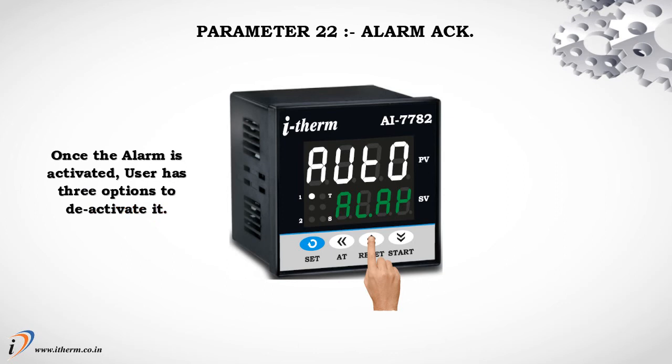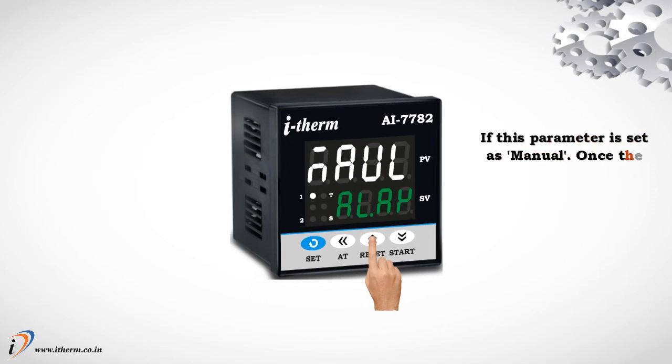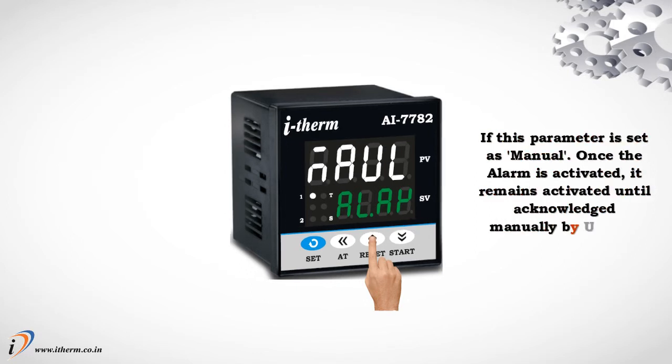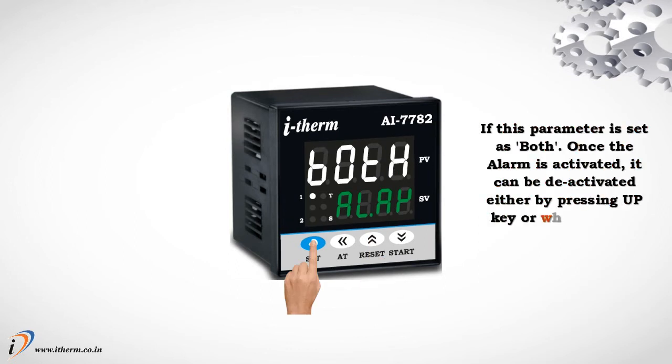Once the alarm is activated, user has three options to deactivate it. If this parameter is set as auto, when process value falls outside the alarm limits, then alarm will be deactivated automatically. If this parameter is set as manual, once the alarm is activated, it remains activated until acknowledged manually by up key. If this parameter is set as both, once the alarm is activated, it can be deactivated either by pressing up key or when process value falls outside the alarm limits.